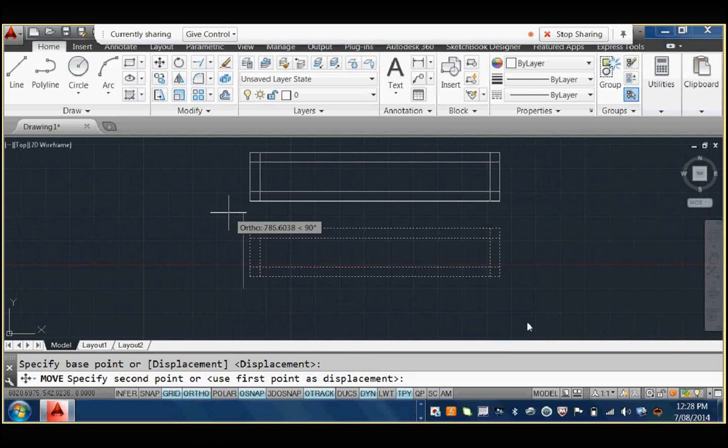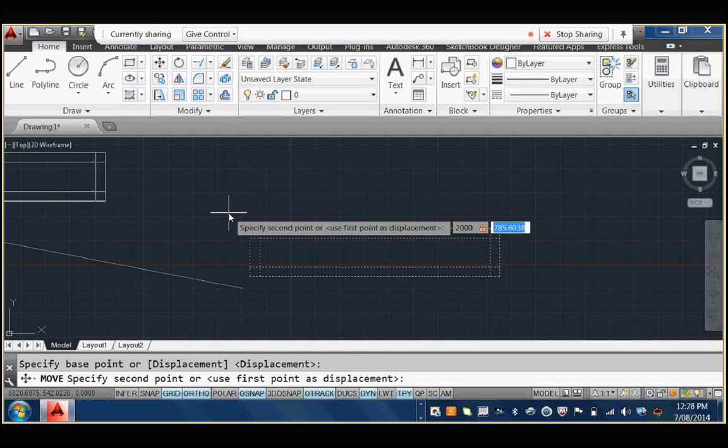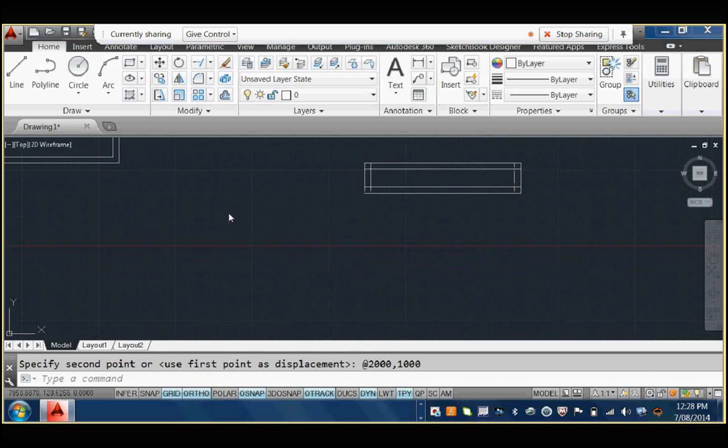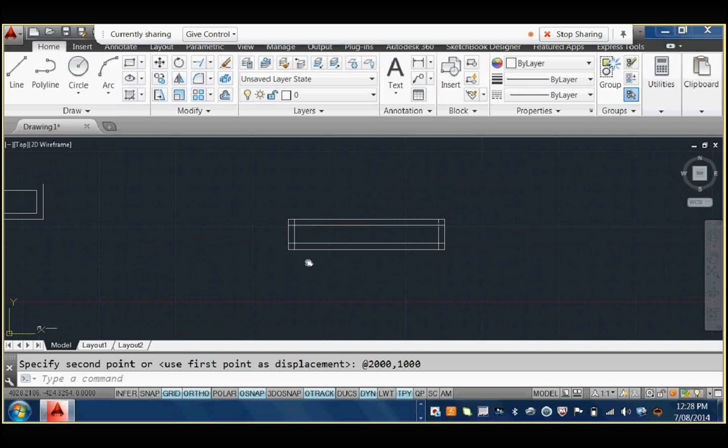Okay. If you want to give coordinates in two directions, the X direction is first. So even if I'm clicking a base point, moving it up relative to that point, even though I'm in the Y coordinate, I would be moving it across 2 meters, and a comma will allow me for my Y direction, and that will be 1 meter. Okay. So it's gone across 2 meters and up 1 meter. Okay. So your X coordinate is always first, comma, and then the Y coordinate.